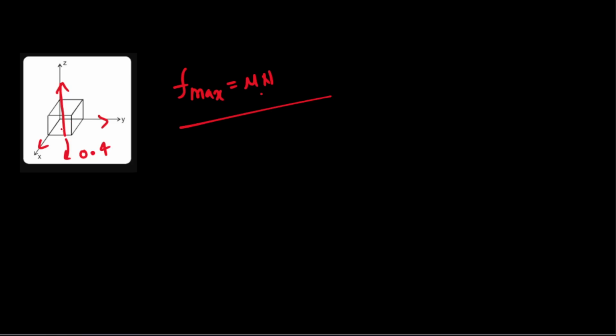After that, you need to check what is the force acting on the body in the XY plane. So that is equal to 10 Newton, the resultant of 8 and 6. So friction maximum which is 12 Newton will not operate, 10 Newton will act.